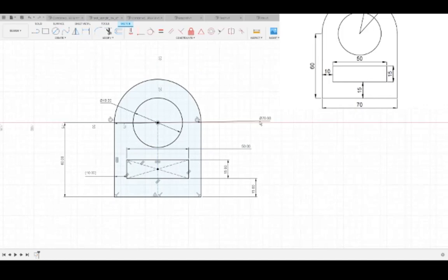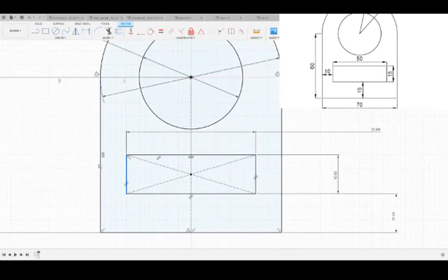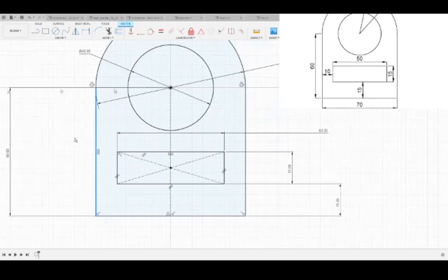So, anyone got any questions about the way I did this, or did I get the point across pretty well? Can you explain driven dimensions again? So a driven dimension. As I mentioned before, your sketch dimensions, besides your geometric constraints, are what actually define the lengths of certain segments of the sketch, the size of certain shapes and so on. However, when all these different segments are already perfectly defined, with a length here, a distance from there, and we know this is centered, there is only one possible quantity that could exist from here to there, and that is the driven dimension, hence why it's called driven.